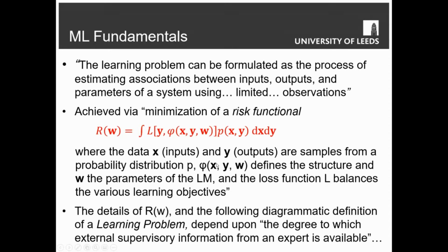In our case, ground truth is not what you might think ground truth is. It may not be the reality in the physical world. In our case, ground truth might be the output of a really high resolution, high fidelity CFD calculation. So we might say ground truth is whatever ANSYS tells us the flow looks like when we solve on a mesh with 10 million volume elements in our finite volume mesh. So ground truth doesn't necessarily mean what it should mean. It means whatever we're using as our representation of the real world.